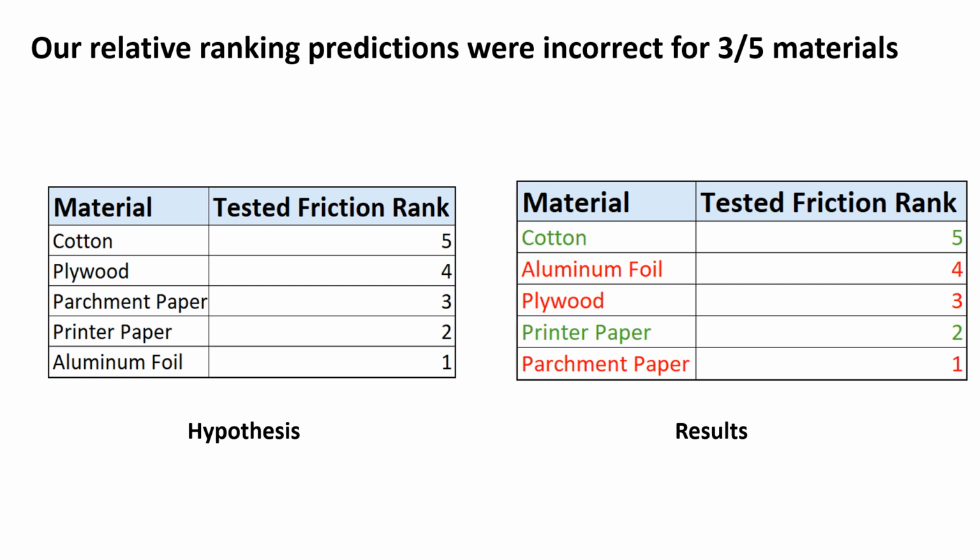When considering this data, it is important to remember that our sample size is small. Due to the time-consuming nature of our data analysis, we only performed 5 tests for each material. For more accurate results, many more tests would need to be completed for each material. However, given the consistency of our data at an evaluation of 95% confidence, this data gives a reliable outlook into the coefficients of friction for these materials.